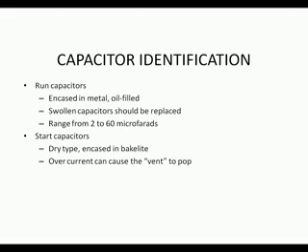Capacitors can be checked either with analog or digital meters. If you're checking with an analog meter, use an ohm meter. Always discharge the capacitor. Either use a screwdriver and touch both terminals together, or use a resistor. A good capacitor will register a resistance reading towards 0, and then the needle will move back towards infinity. If there's no reading, reverse the meter leads. No needle movement indicates an open capacitor. A reading of 0 ohms indicates a short circuit.